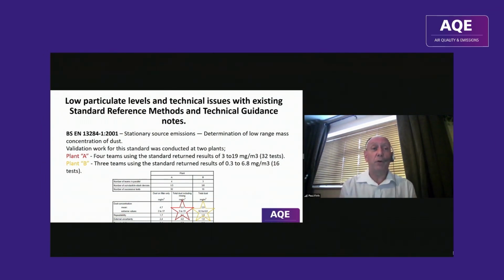And just to give a bit of an overview on the standard, when the 13284 Part 1 standard was first developed back in 2001, like a lot of standards, like Rod has covered already, validation work was completed on this standard at two plants. They were both municipal waste incinerators. Plant A was a semi-dry process with a fabric filter and a stack gas temperature around 140 degrees. As part of this validation work, 4 teams tested the same stack at the same time, and the results varied between 3 to 19 milligrams from 32 tests.